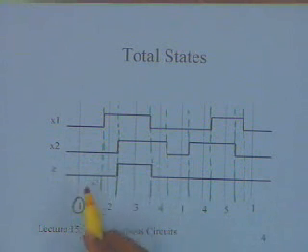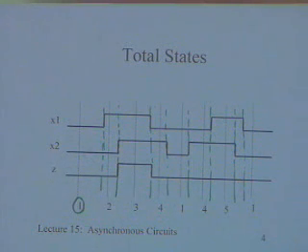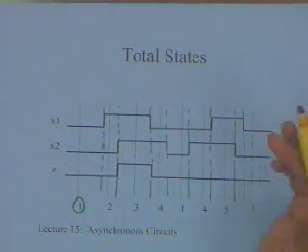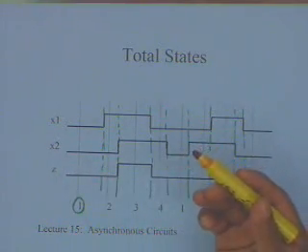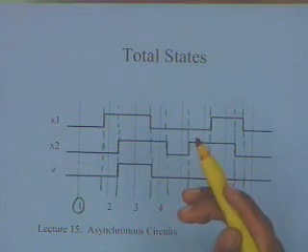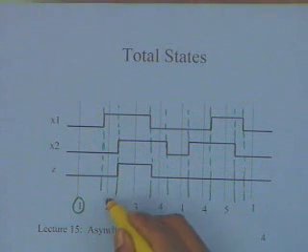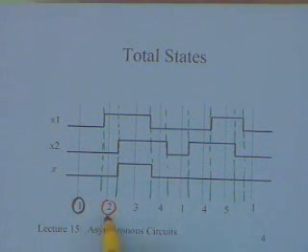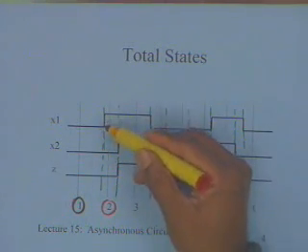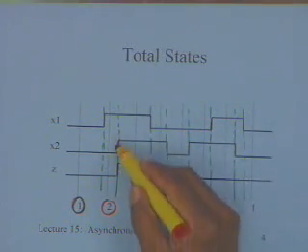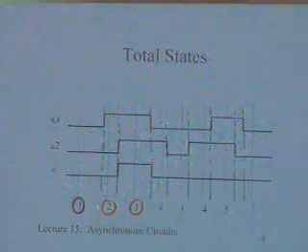The reason I call this a stable state is, if no input changes occur, nothing will happen to the circuit. That is the definition of this. If the inputs stay at x1 and x2 both 0, it does not matter for how long, z will also remain 0, these two will remain 0 and nothing will happen to the circuit. But now I change x1 to 1 and I go into a stable state called 2. I may go through some changes in between, we see that later, but I will be in stable state 2. Now when this change occurs, I go to stable state 3.